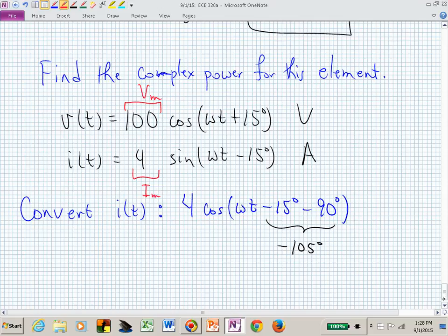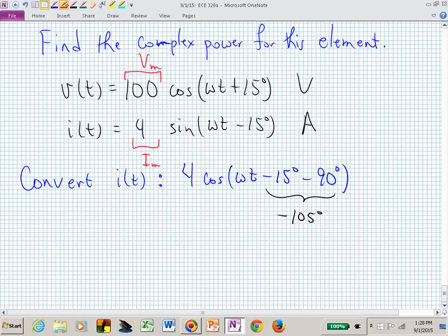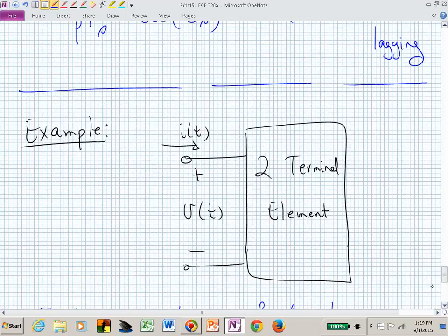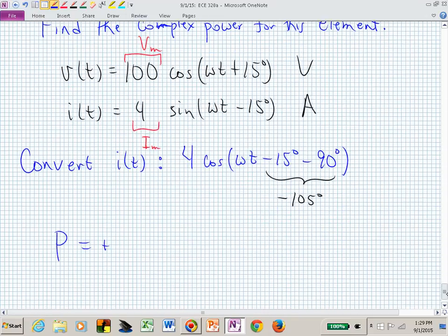And if those are in units of peak, now if I wanted the average power, or the real power, of that two-terminal device, I now have plus, since the passive sign convention is in effect, right? I have a positive, since I is going into the positive voltage terminal. And since these are in peak units, there's the 1/2.